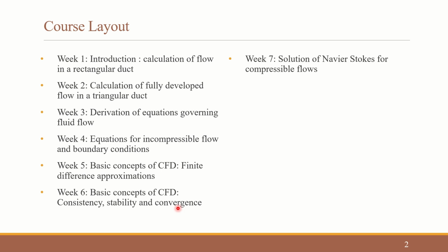In the last 2 weeks, we saw the solution of Navier-Stokes equations. In the week before last, we saw the solution of Navier-Stokes equations for compressible flows, and in the last week, for incompressible flows. For compressible flows we have methods like the MacCormack scheme, the Beam-Warming scheme, and so on.